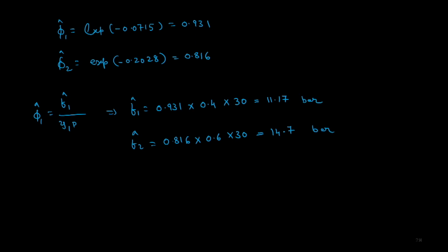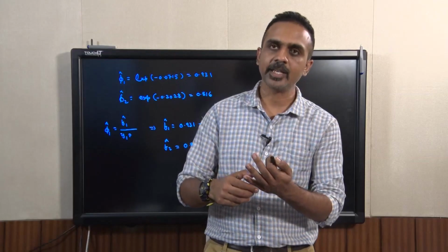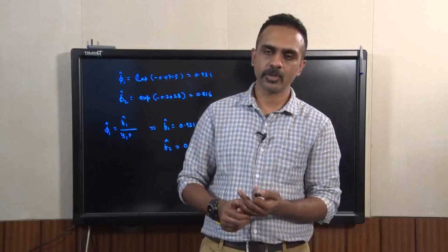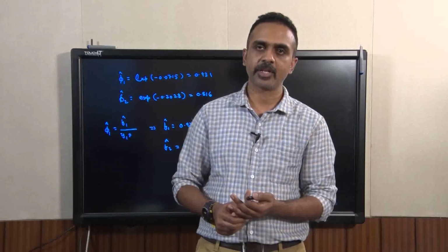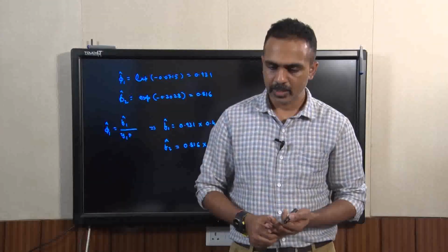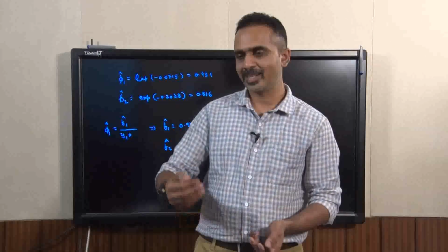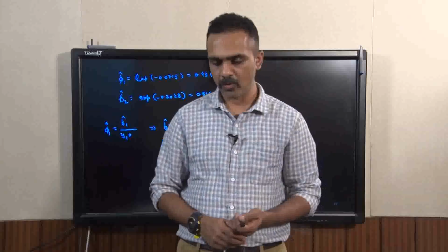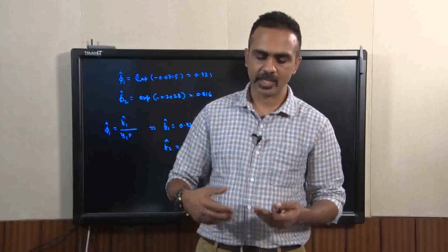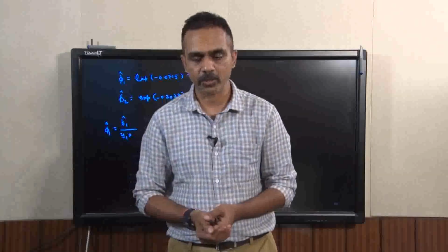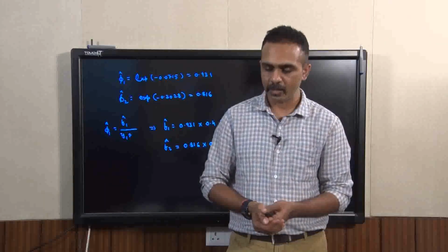So we go through the series of steps, first to calculate the cross virial coefficient and the pure component virial coefficients after obtaining the pseudo-critical parameters using the combining rules. And once we do that, the rest of it is pretty straightforward to calculate the fugacity coefficient and hence the fugacity of species 1 and 2 in the mixture.